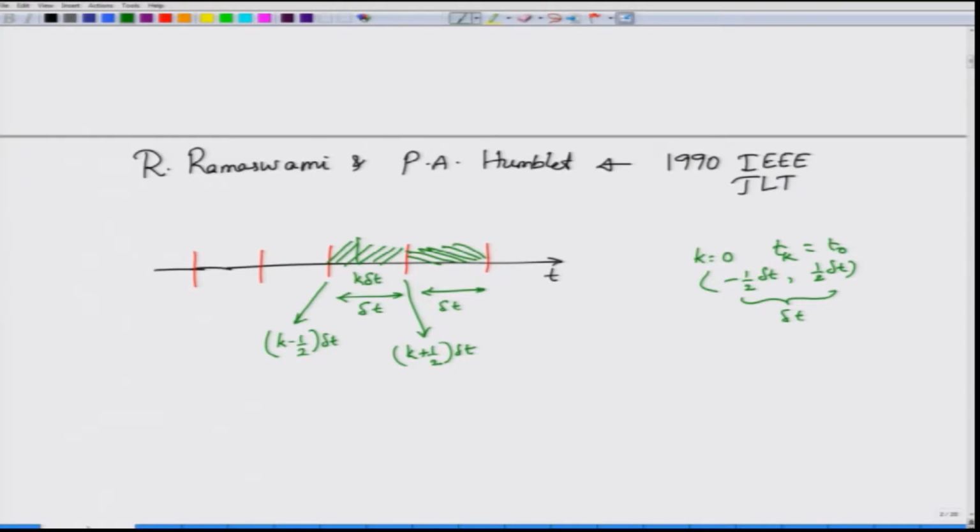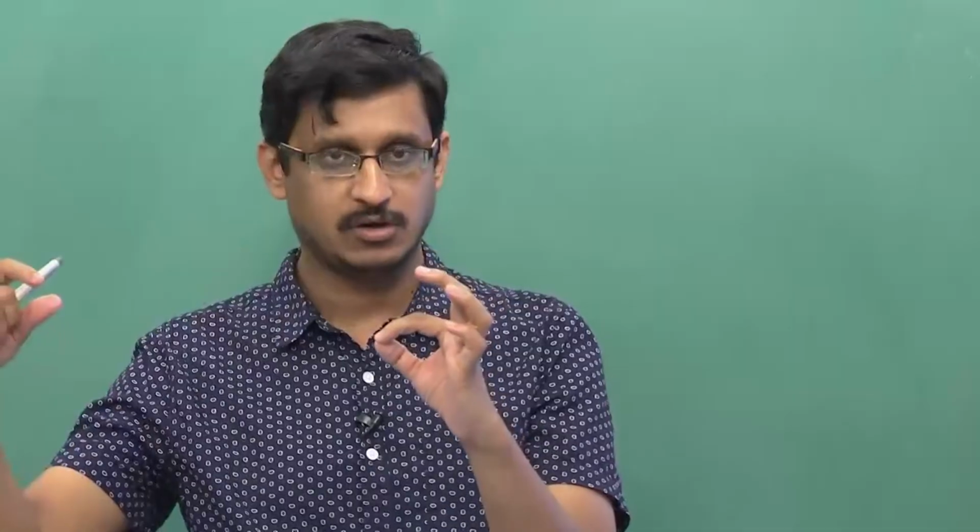In these non-overlapping intervals, let us imagine that at each interval I am going to get some number of electrons generated. Where are these electrons generated? It is in the photodetector, right. The photodetector has to look at the number of photons coming in, and each photon will generate a carrier based on the quantum efficiency of the photodetector. So if the quantum efficiency of the photodetector is eta, then eta times the photon number would be the number of electrons, or electron-hole pairs, that are generated.